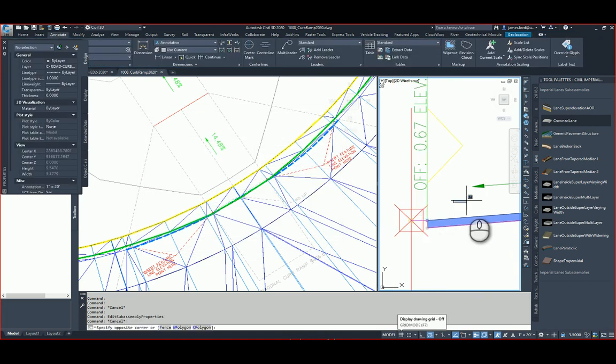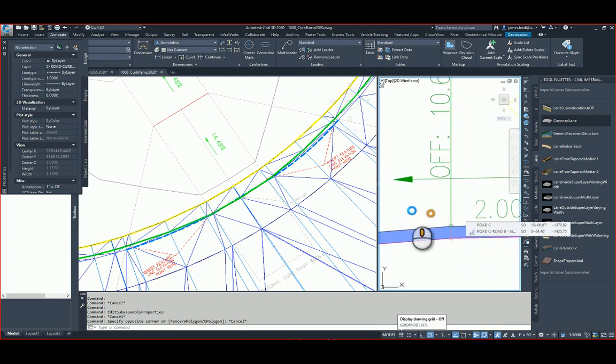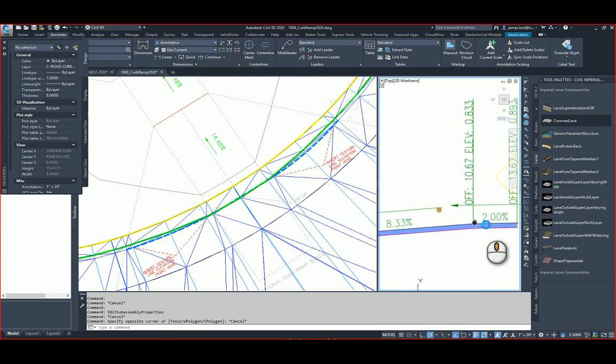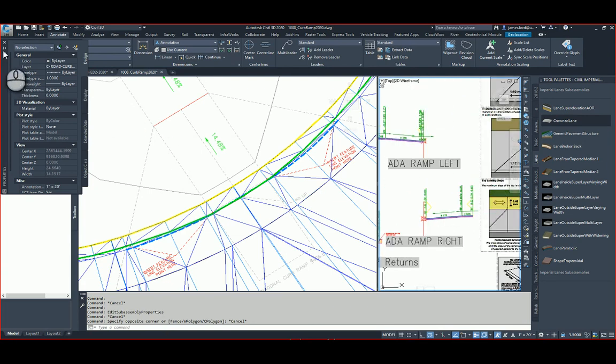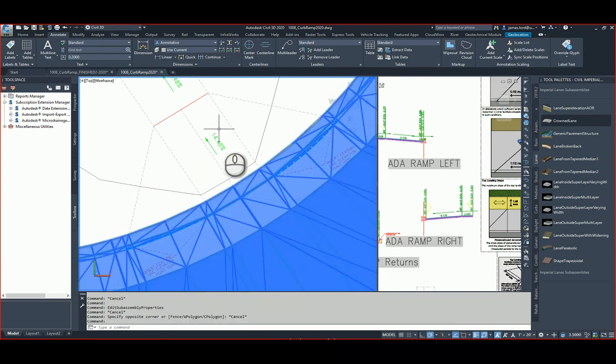And then if I zoom out just a little bit more, I used another piece of pavement on the end here and basically attached it to the ramp to give me my landing pad. So this is how I built my ramp. So how are we going to add this in is we're basically going to click on that corridor again, and we're going to go into the corridor parameters this time.